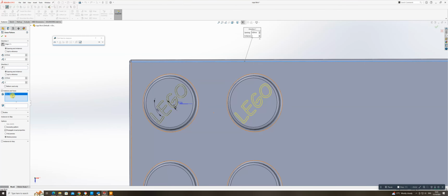The reason it's gone across to exactly where I want it is because it's 8.05. Your default will be 10. So if I change that to 10, which is what you'll have, you'll see it's actually not on centres. That's why I needed to know that distance, and you can measure that. So just change that back to 8.05.